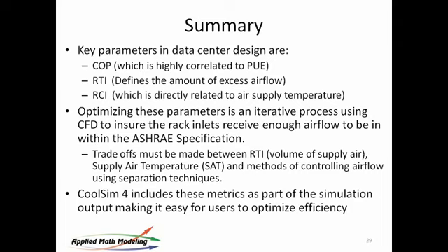We then optimized these parameters in a process that used CFD to make sure that whatever decision we were making would work and still keep our racks within specifications. And you do need to make some trade-offs between RTI, supply air flow, and supply air temp to make sure that they are balanced. And you can do this all in CoolSim, making it really quite easy to optimize.